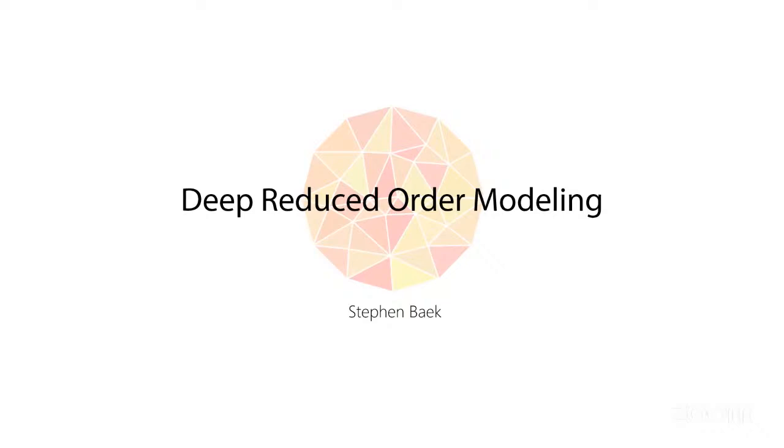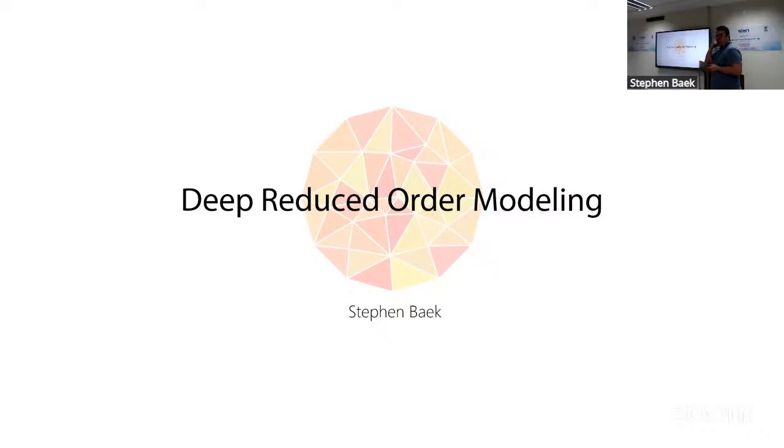So, today we're going to be talking about reduced order modeling, or ROM. The idea of reduced order modeling is that a lot of physics simulation data or experimental data are in some high dimensional space, okay, and because of the dimensionality, computationally it's very expensive, and also you may actually miss a lot of important trends by looking at only those high resolution small local regions. So the idea of reduced order modeling is to reduce the dimensionality of the problem and then learn the physics over there.